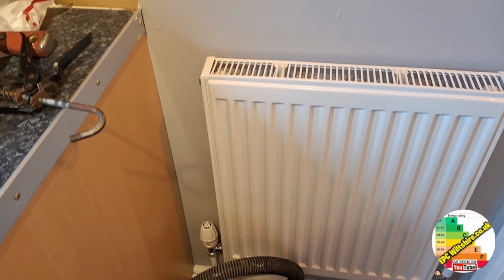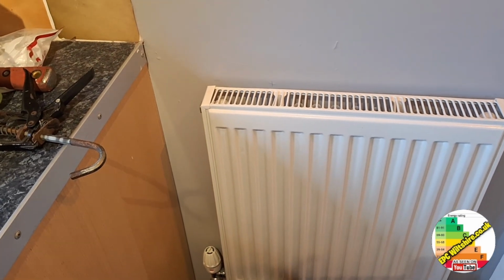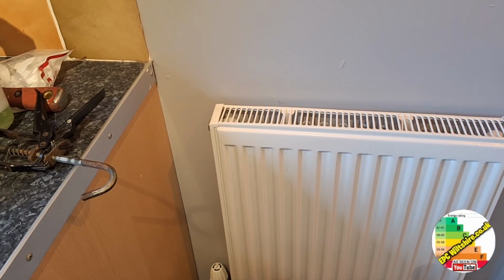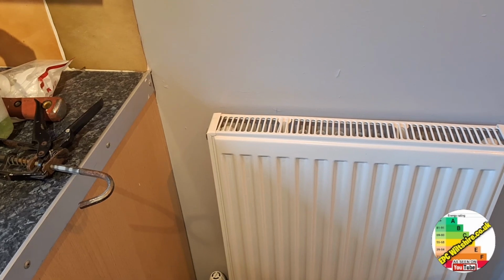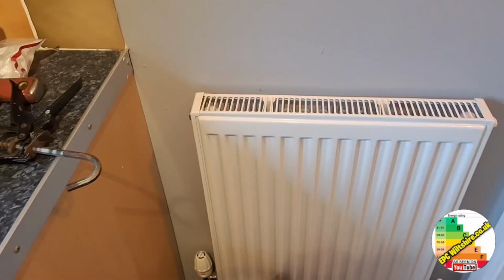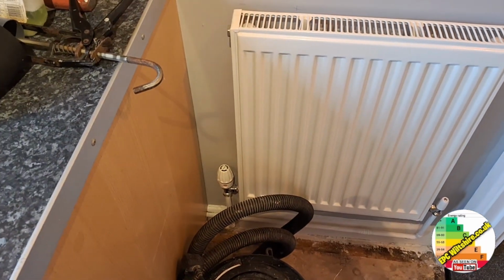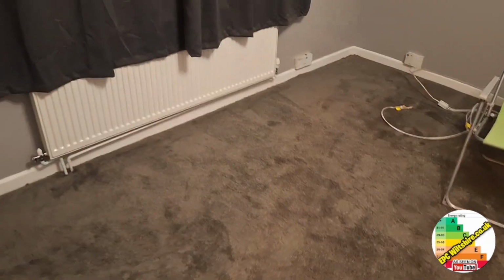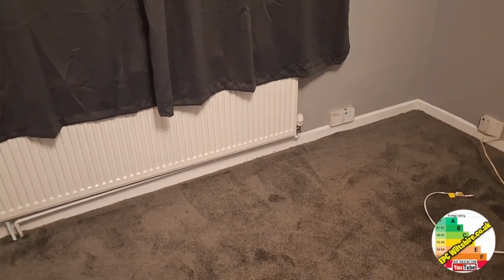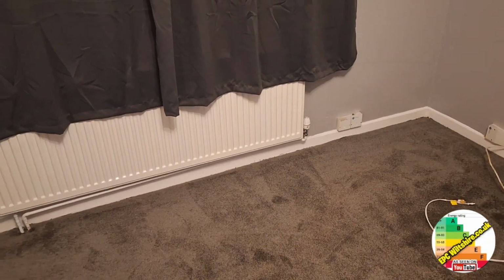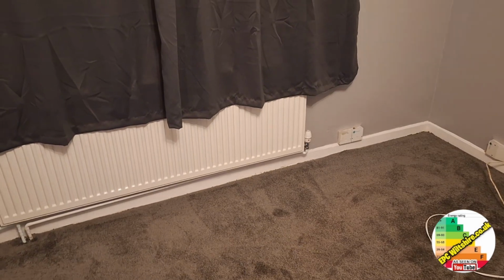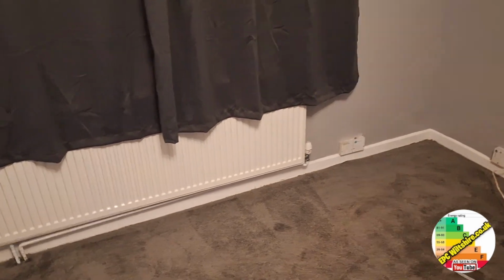So we know we don't need to do the thickness of the glazing. It was only unknown date or pre-2002 that you need to do the thickness of the glazing on a UPVC window. Thermostatic radiator valve on this radiator, another thermostatic radiator valve on this radiator. So more than 50% of the radiators have TRVs, so we have TRVs.